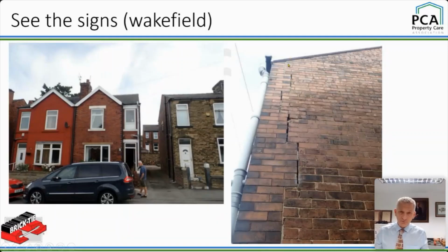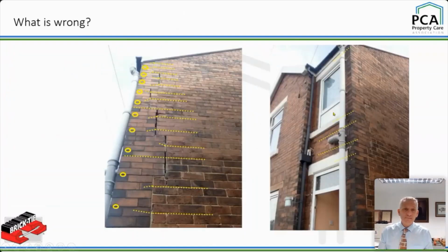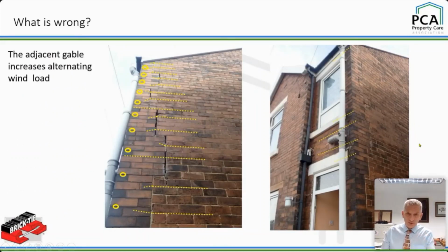It's used good bricks at the front, bad at the back. So we've got a poor bond there anyway, and pointing is dropping out because the walls are moving differentially. Okay, in addition, and what went wrong, we've got the wind loading.